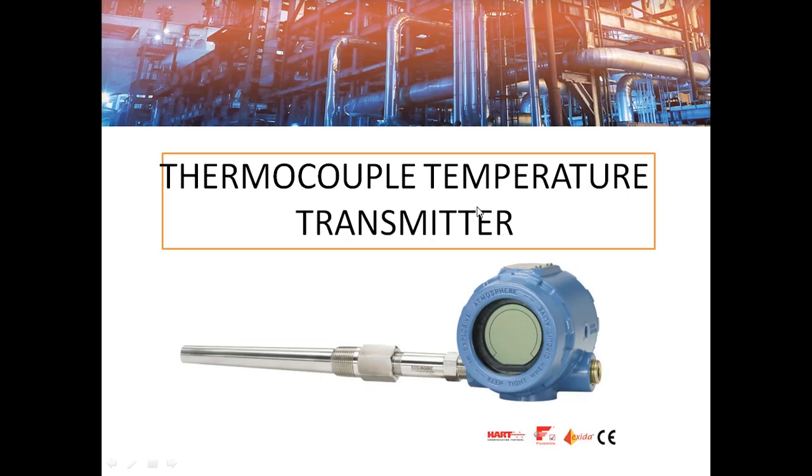In this video, I am going to discuss the thermocouple temperature transmitter with respect to data acquisition. That means how the thermocouple signal is received by the transmitter and how it is converted to a temperature value. Transmitters are widely used in industry for converting the sensor output to a 4 to 20 milliampere signal, and this 4 to 20 milliampere signal is transmitted from the field to the control room where the control system is located.